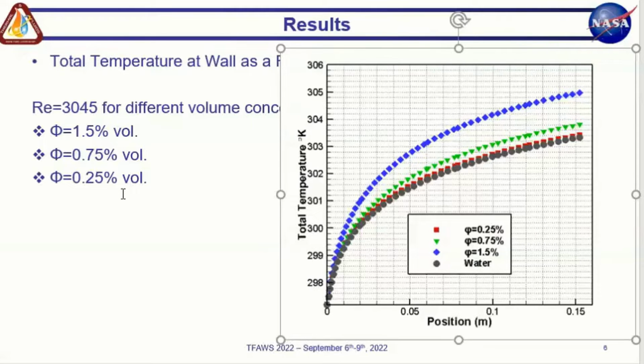Now, the heat transfer coefficient is a complex function of many variables. So I can say, for example, it wouldn't be surprising to find out that the heat transfer coefficient is a function of the particle size, for instance, because there is mechanical mixing, there is dispersion of the nanoparticles as they swim and bounce and so forth in the base fluid.